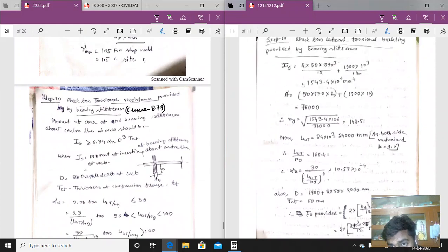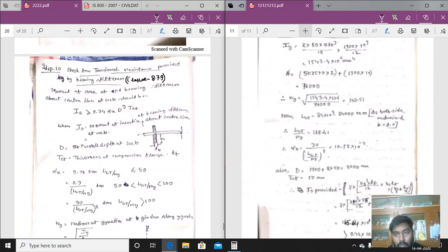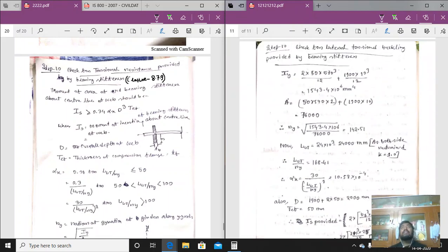Now one thing I would like to say here, when I did this math for you in the torsional capacity, first I assumed the end bearing plate size 200 into 25. So that plate failed. Then I assumed another bearing plate. In the exam, after assuming this, if the torsional criteria fail due to shear buckling, we have to provide a torsional stiffener also.